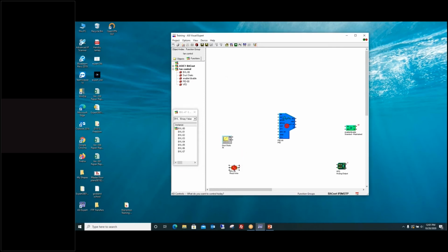And then the last one you need, go to the objects box and pick AV. Oh, you closed the box, so right click. There you go. So scroll up to analog value. That's analog out. I want analog value. Okay. And then drag the 0 down kind of lower, right below the VFD or near the VFD.